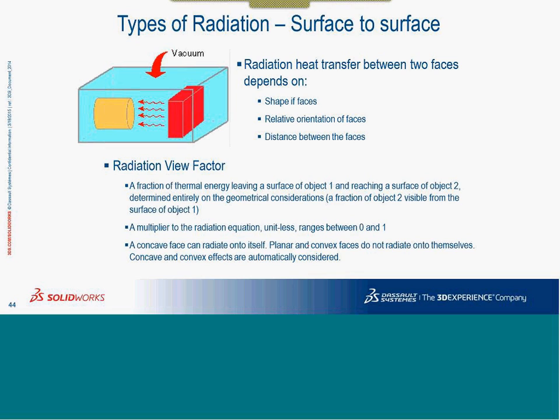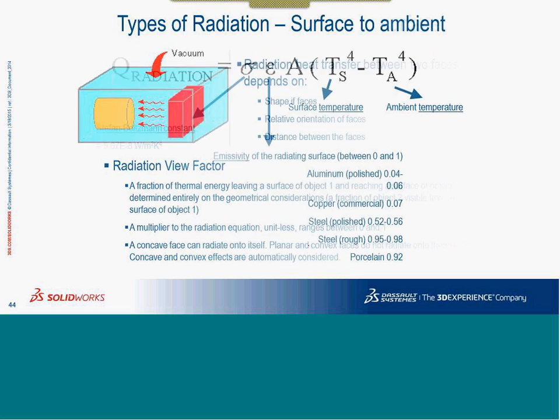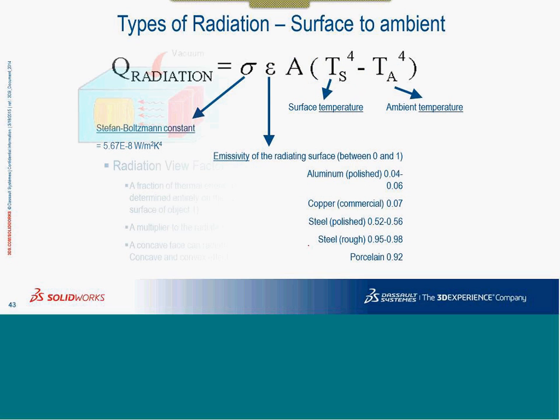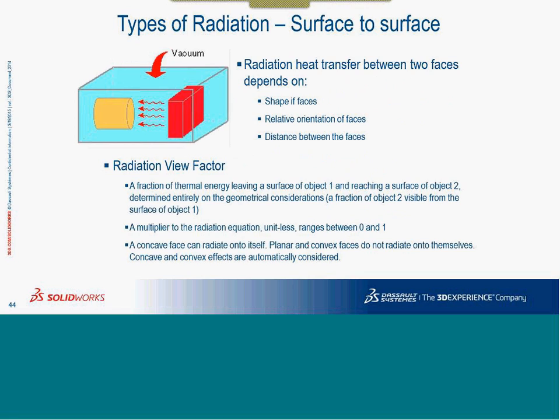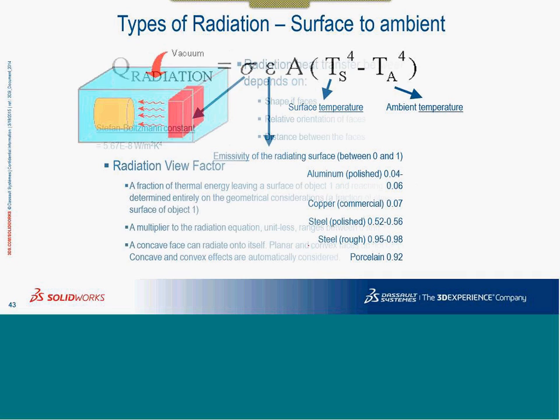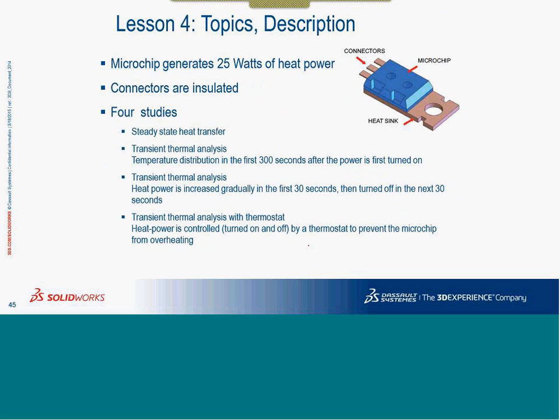In Simulation Professional, we are directly giving these inputs in the form of the constants discussed in this slide, and it calculates the flux, whereas Flow Simulation has a few more capabilities where it does calculate the heat transfer coefficient and other details, whereas in Simulation we need to give those inputs as a normal property. So I think we are going into the example or the setup. Before that, any questions, guys, as of now?